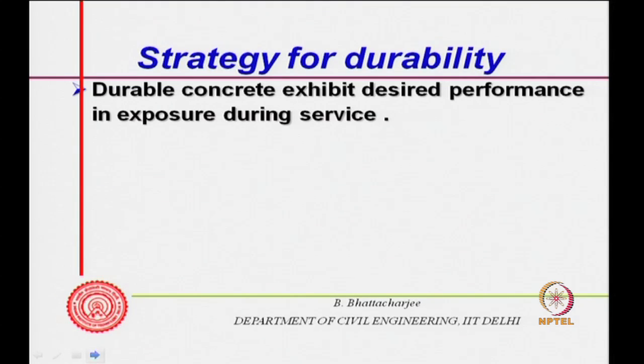Currently, our understanding of the physical phenomena and physical models for deterioration is really very limited. Possibly carbonation is a function of the square root of time, which is experimentally validated. Many things could not be experimentally validated because of the long term required. Accelerated tests quite often may not actually represent the real situations.